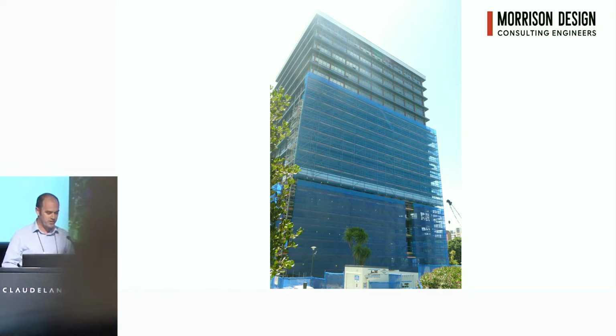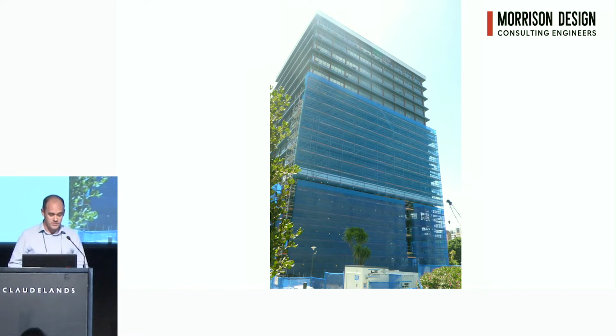This is a photo earlier on in the construction, and the bottom section of scaffold here is actually independently supported from the top section, so they can remove that bottom section and just leave that middle section in place. As you might imagine, the design of this sort of scaffold has a high consequence of failure. So we really need to be thinking about redundancy and alternative load paths with a scaffold like this.